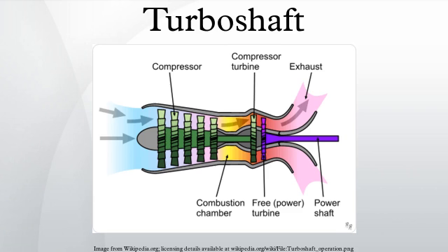A turboshaft engine is a form of gas turbine which is optimized to produce shaft power rather than jet thrust. In concept, turboshaft engines are very similar to turbojets, with additional turbine expansion to extract heat energy from the exhaust and convert it into output shaft power. They are even more similar to turboprops, with only minor differences, and a single engine is often sold in both